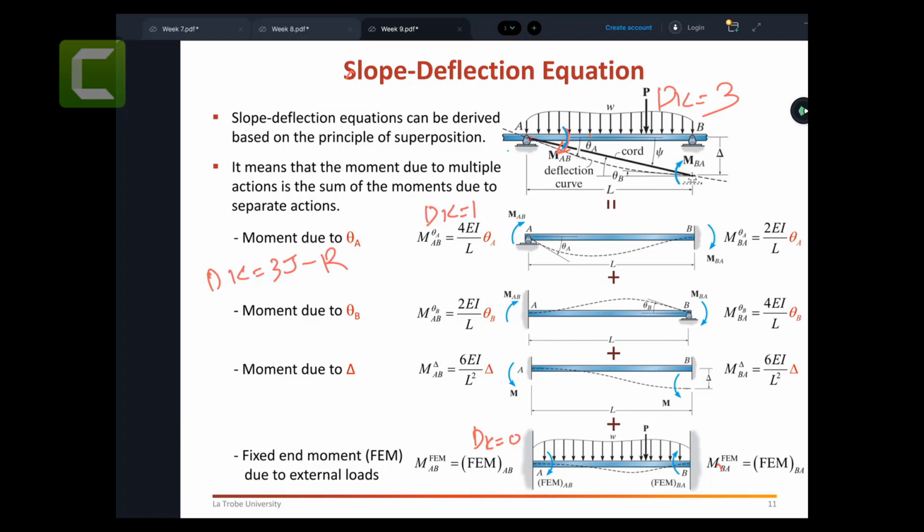So what have we done? Somehow someone goes there and removes 1 or 2 nails and removes that plate. That removing of the plate allows that point A to rotate theta A. Immediately when you rotate theta A, you need moments to rotate it. Let's forget about theta A. Let's say someone wants to rotate that joint by 1 degree, because theta A is quite complex.